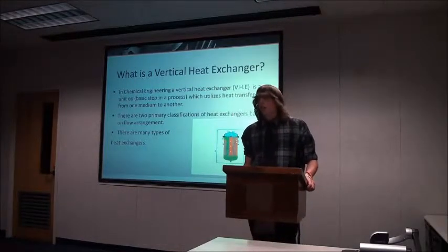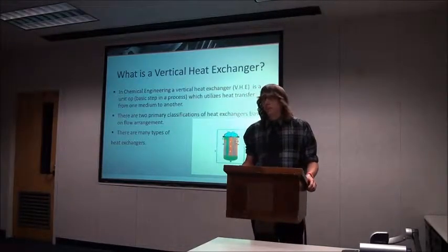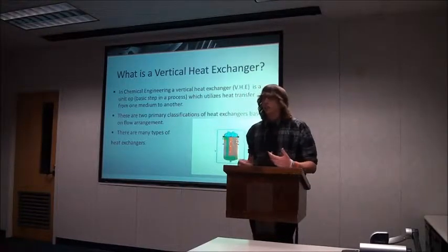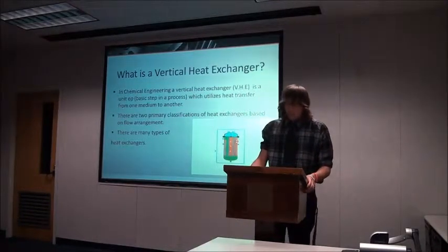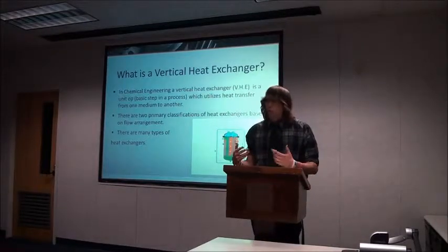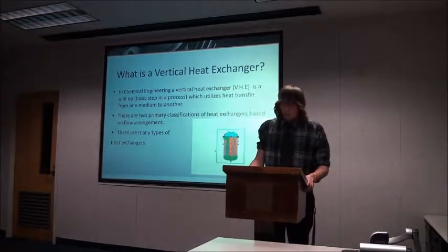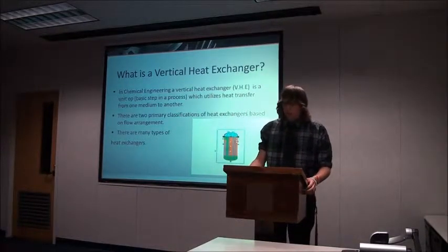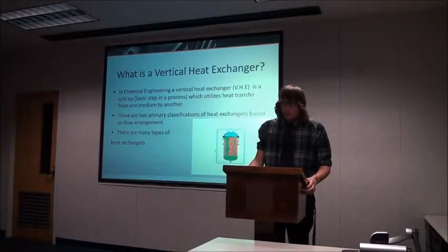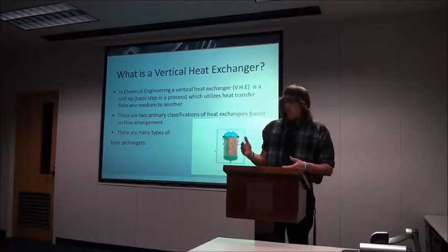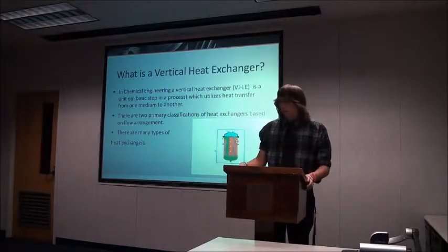The countercurrent design is believed to be more effective, and usually is more effective, in that it can transfer the most amount of heat from one medium to another, because the average temperature difference is greater than in parallel all the way through.